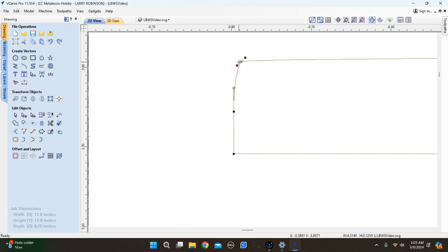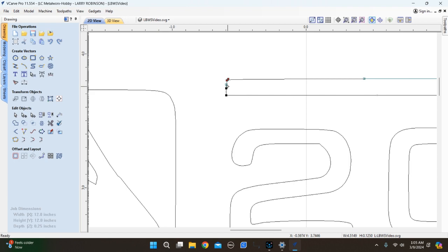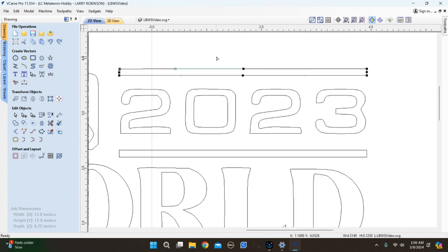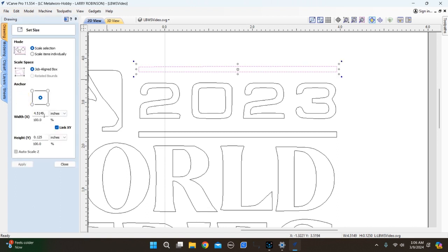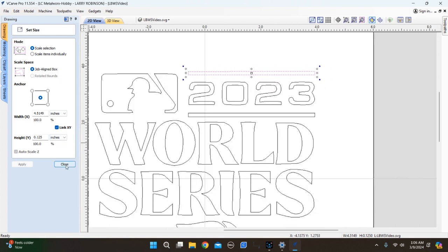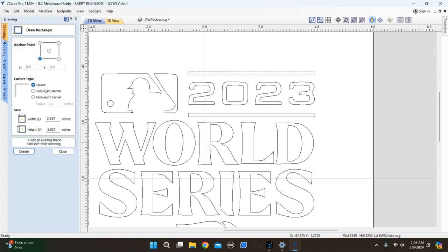To me, it'd be hard to fix that. Personally, I would rather go in and just kind of redraw some of that. That's just a rectangle. So honestly, the same way I showed you earlier, you could go in, check what size that rectangle is. It's 0.451, well, 1/8 of an inch. So actually going into a rectangle, and we say 0.451 and 125,